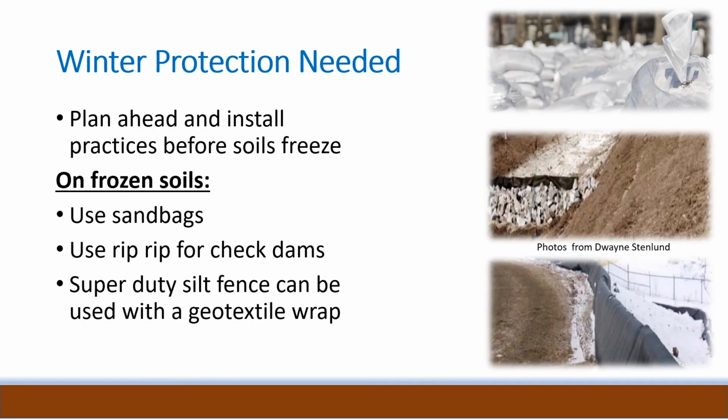A reminder to button up construction sites for the winter. So plan ahead and install practices before the soil freezes. However, if you have to deal with situations on frozen soils, you could use sandbags, you could use riprap for check dams, you could use Super Duty silt fence that can be used with a geotextile wrap. So you have options.